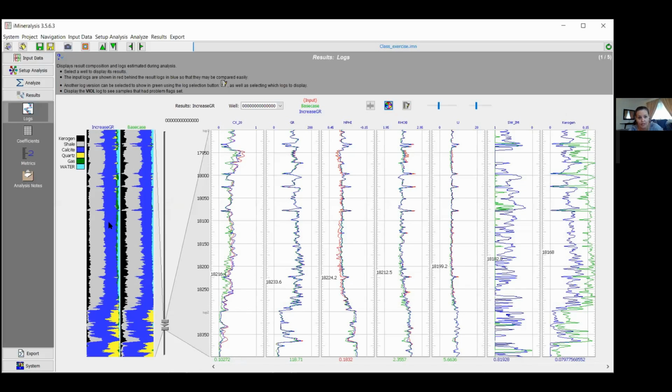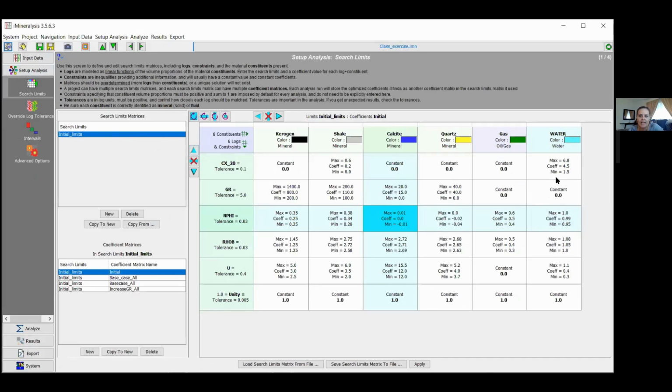So one thing that I noticed too is that the conductivity is being matched, but it's not perfectly matched. So I'm going to change the conductivity of the water. That's what I emphasized when we were in the PowerPoint, that the conductivity of the water could be higher. We're in the deep unconventional reservoir. So I'm going to go ahead and change that to 5.5. I'm going to actually do it twice. I'm going to change it to a higher value later on.